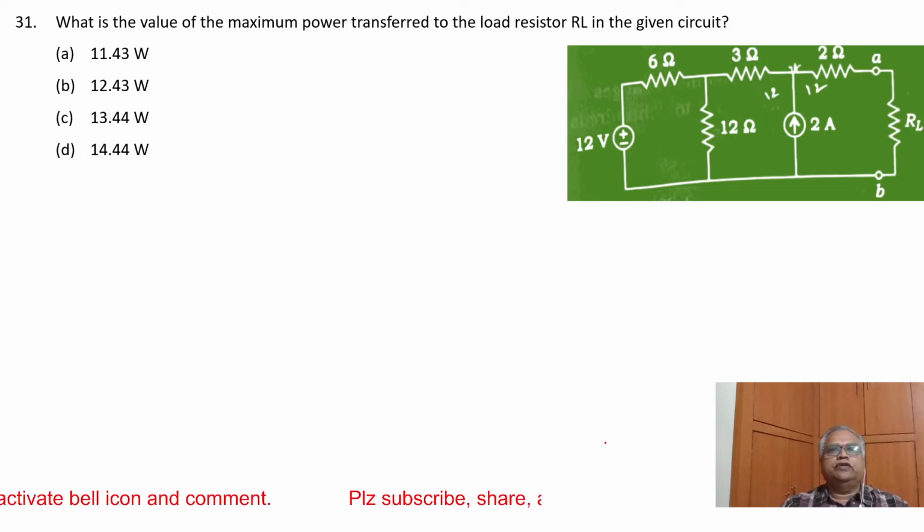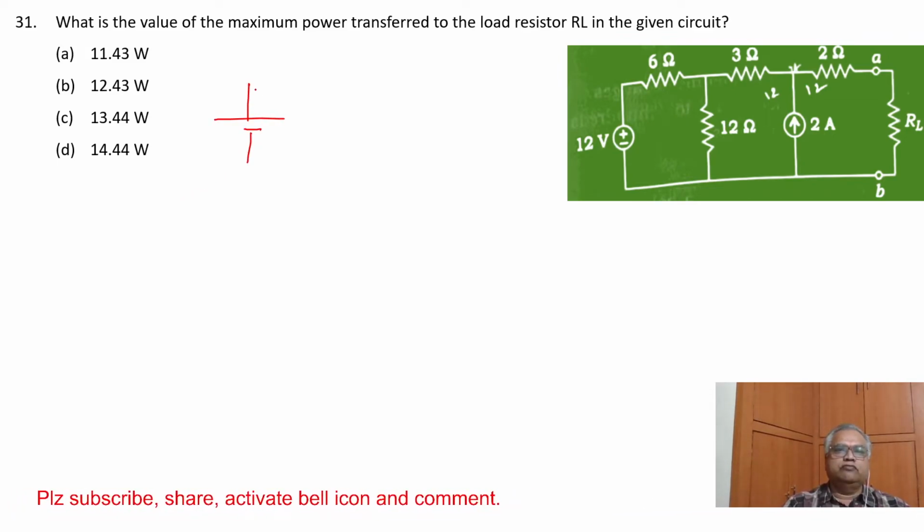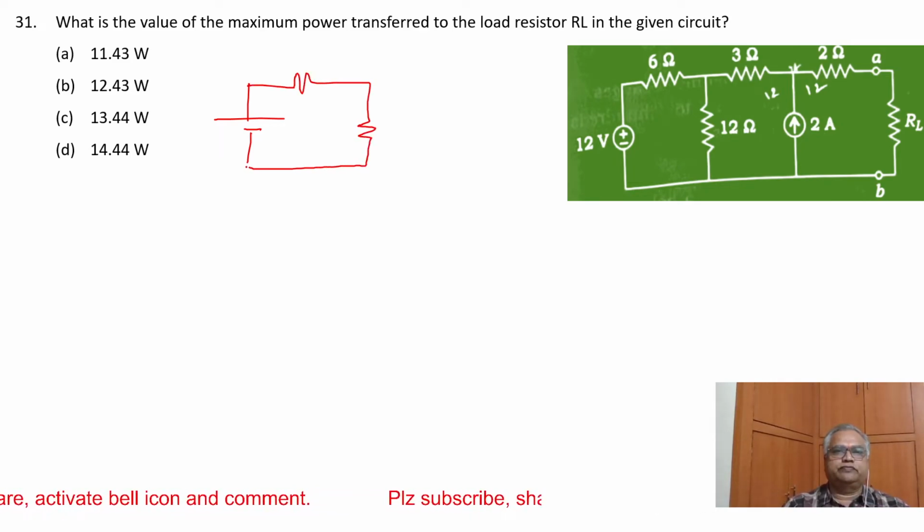What is the value of the maximum power transferred to the load resistor RL in the given circuit? We have to clearly use Thevenin's theorem here. The maximum power transfer theorem is an extension of Thevenin's. We have to find the Thevenin equivalent first, V Thevenin and R Thevenin, then connect the load RL.